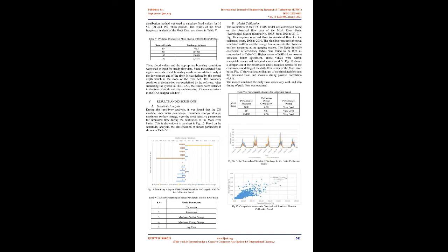Calibration procedure was carried out manually and also through optimization techniques to match the observed values and simulated values. The manual calibration of 7 parameters was performed using observed streamflow data from the Modi River Station, Station No 406.5. The calibration was initialized using ranges obtained from the previous research studies 23, 24, 25, 26.